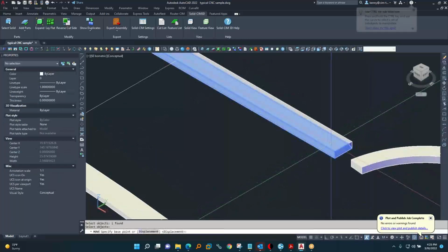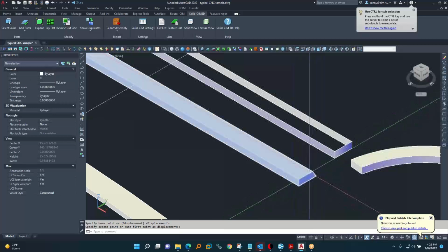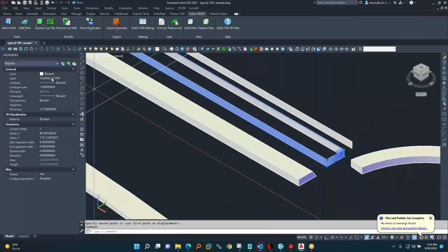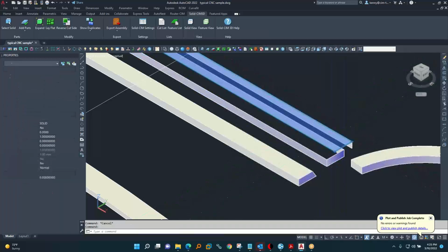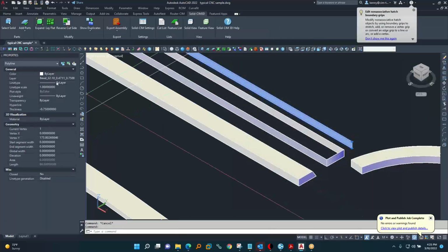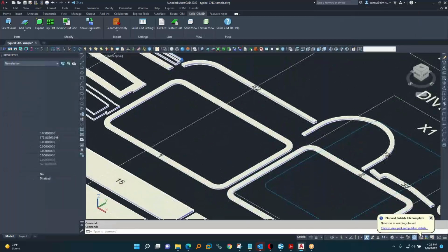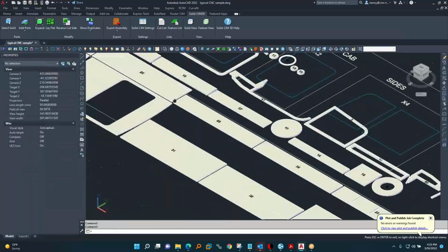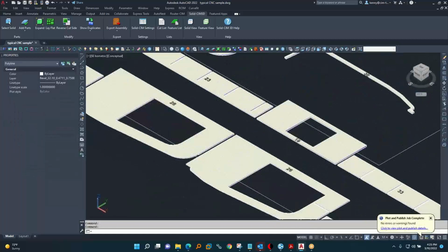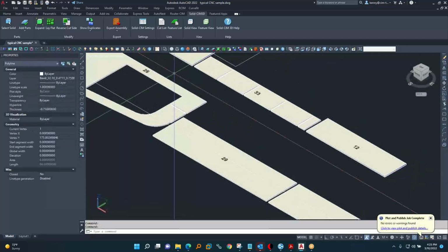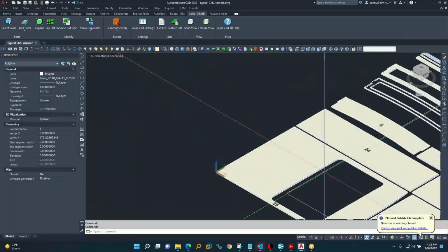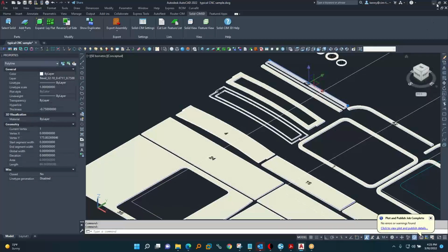So it made those two pieces of geometry for us automatically. Here's a piece that's interesting. So I moved this solid out of the way. It had a bevel on there, right? So this made me a layer outside and a layer called bevel. Right there, this is on a layer bevel. So you could take a bevel tool and cut along that edge. Any of these models have dados or drilling operations, I don't see any that have dados or drills, because those would be recognized as well as horizontal operations and any kind of side operations on the side of the part.